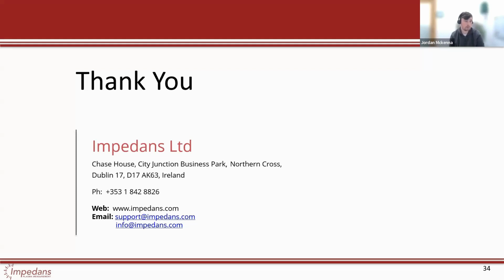What is the detector bandwidth? Can it work with variable frequency RF generators? Yeah, it can work with frequency generators. The way the sensor works is it has either 10% or 2 megahertz, whichever is smaller. So above 20 megahertz, the bandwidth is 2 megahertz, but below that, it's 10%. So that is the bandwidth there.